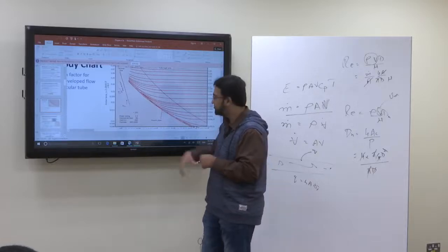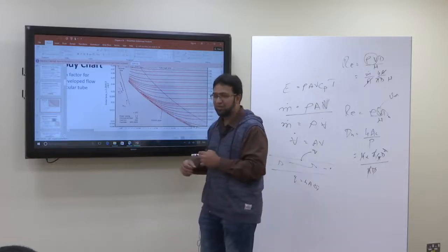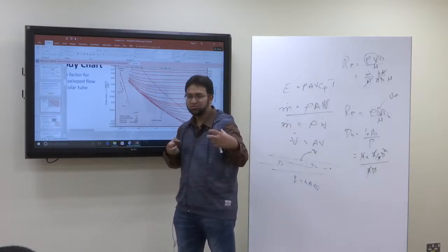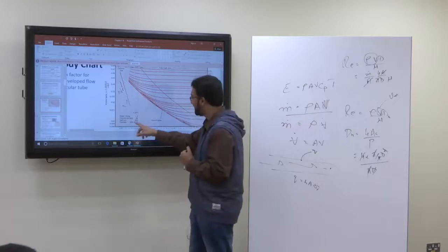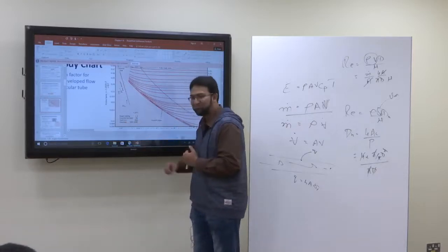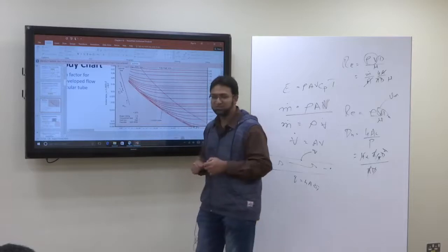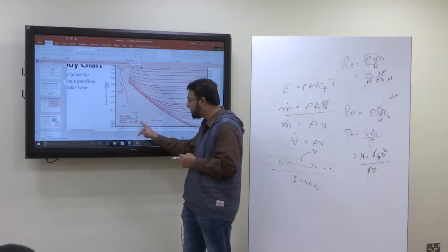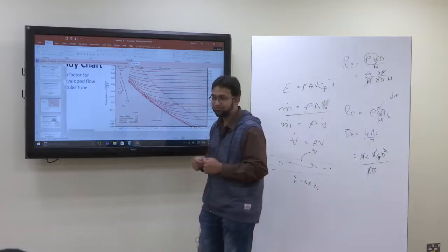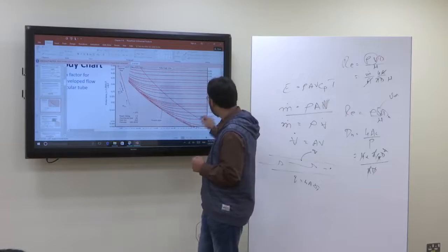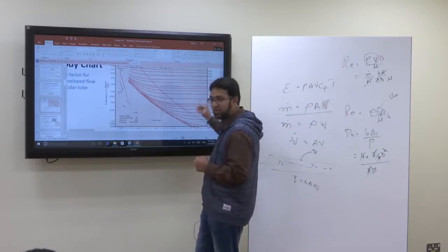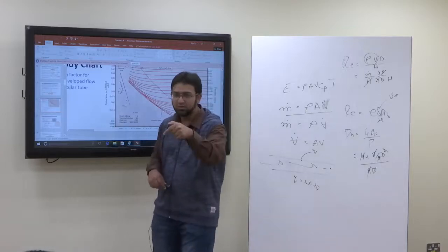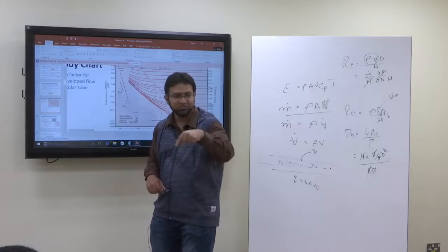What is drawn tubing? It is a pipe made by the extrusion process. If it is cast iron, the roughness is 260 micrometer. If it is concrete, the roughness would be between 300 to 3000 micrometer. Anyway, this is the relative roughness. Suppose you know what pipe you are using. Roughness is a parameter of the material, so change the material, and the roughness will change.